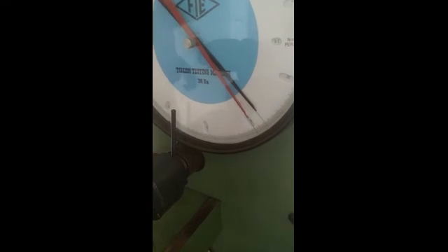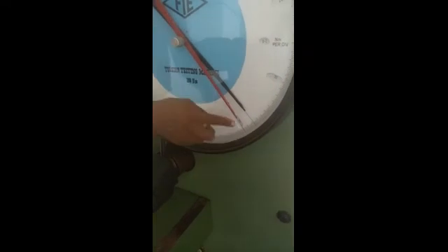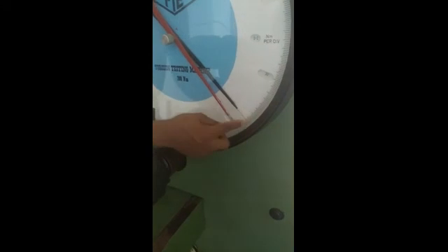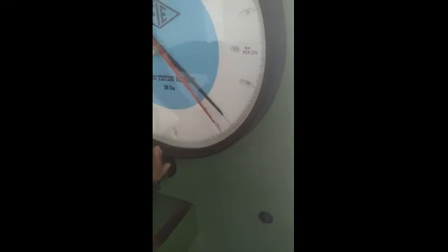We can see here the twisting has started. We have applied that chalk, because of that we will come to know that twisting is going on in the material. Next, by using the motor we can take the reading. You can see this needle came back, so the position whatever we can see here, that we have to consider as the lower yield point. This is the upper yield point, this is the lower yield point, because the needle moved slightly back. Again from that position it comes forward.